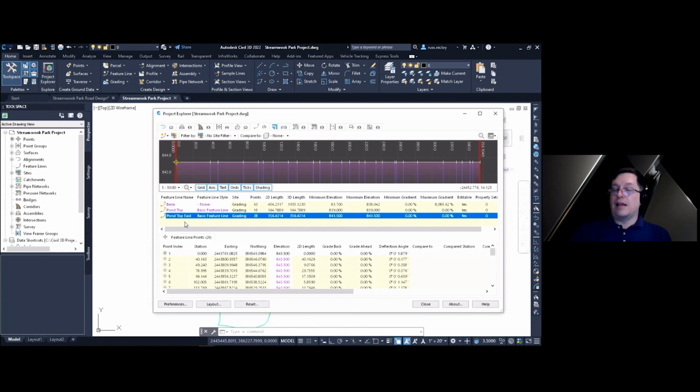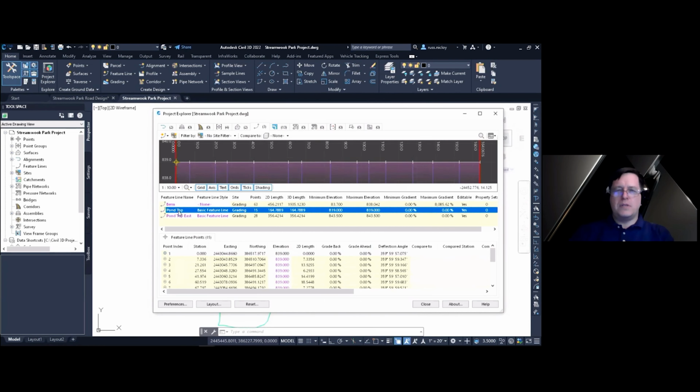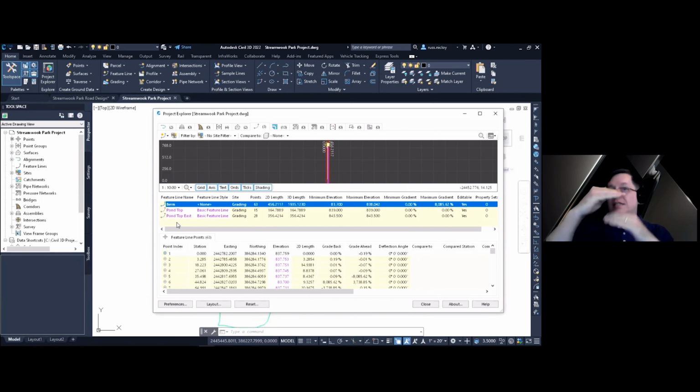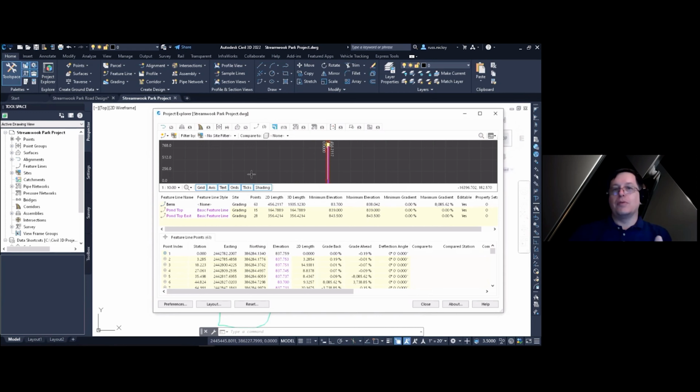Now, first of all, I really like that because it helps me understand where the slopes are and where things are in relation to each other elevation wise, not just the horizontal look of it. But as I'm going through these, generally I'm seeing a kind of a profile look to it. When I get up to the berm, I notice, wait a second, something doesn't look right here. What has happened here is somebody entered something incorrectly or tweaked something incorrectly, maybe snapped to something that they didn't intend to. And now the profile view, that preview, is taller or deeper than it is wide.